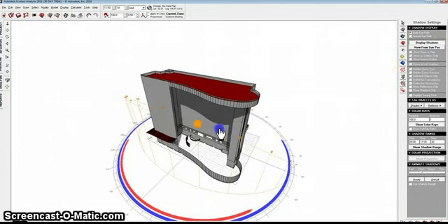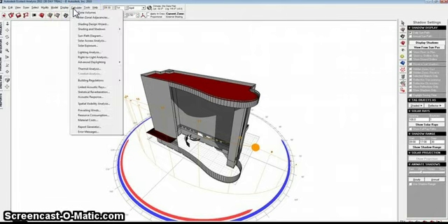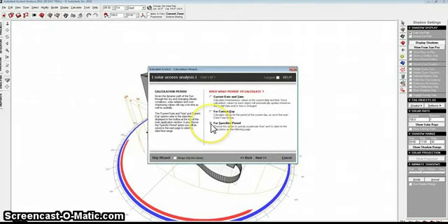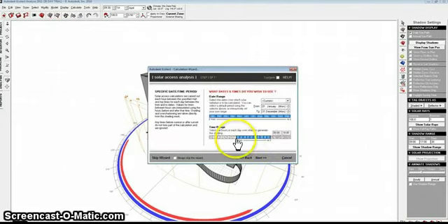And to upload the climate data, you just go up to the top of the screen here, and you'll click the little globe. But first we're gonna calculate some solar analysis. Solar access analysis right there. Click, and it's going to bring you through a number of options. Choose the first one. For specified period, we're doing daylight hours for the whole year.